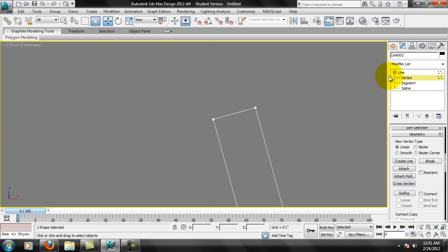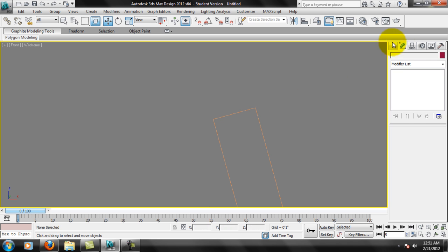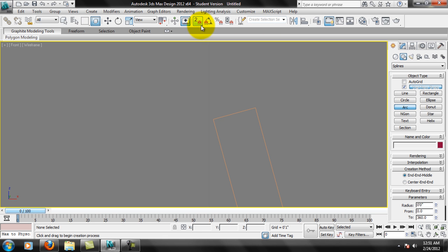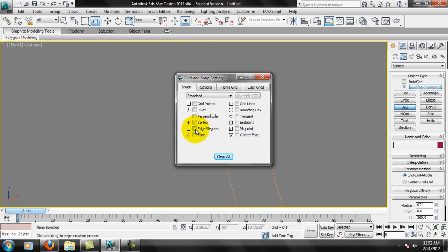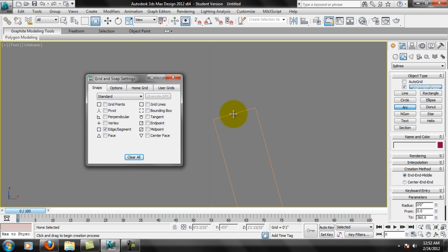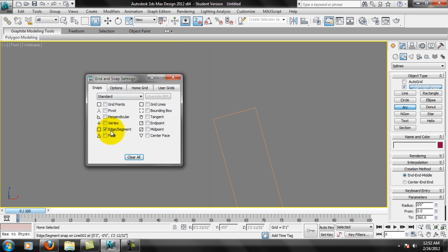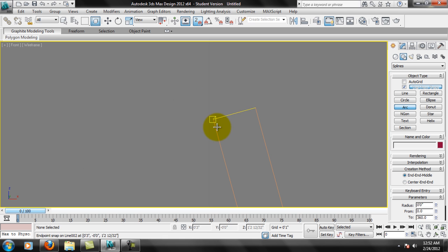So basically, to do this, we're going to have to create a whole nother line. So I'm going to go to New, and I'm going to create an arc this time. And I'm going to turn on my snaps, but I want to make sure that I turn off grid points and turn on edge, because I want to snap to the edge points of this. So I need edge snap to be on. And I have arc, and I need to turn this on. And there's my snap to those points. Actually, I lied. Not edge. That doesn't make any sense at all. Just strike that and select endpoint. I apologize. So we want endpoint to be on. Edge was almost like near. So now we're snapping. Now we're cooking with some gas.